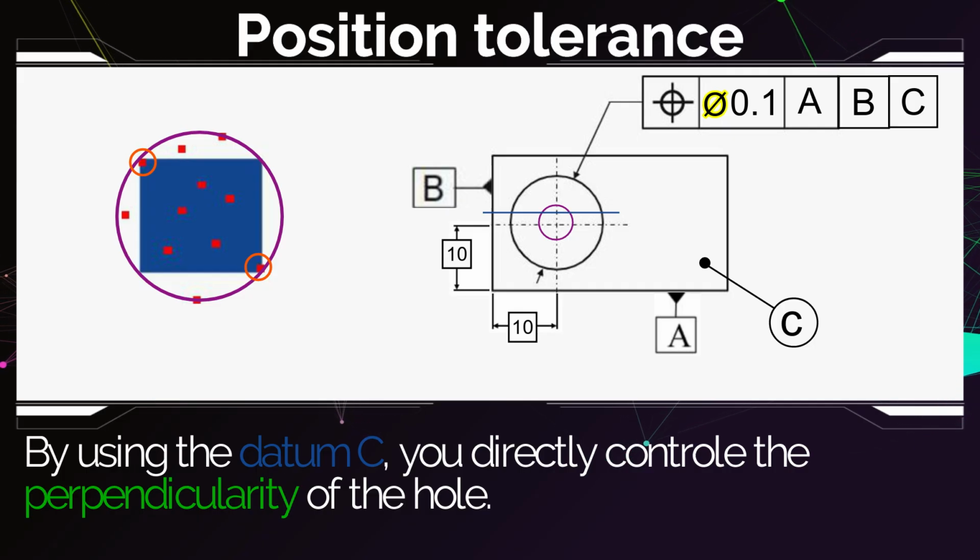So why did you refuse this point, although it lies on the same distance from the center? The effect on the function is the same, but in this case you had to refuse it because it lies outside your tolerance. But using the diameter sign, you allowed all this extra tolerance zone without negatively affecting the function.